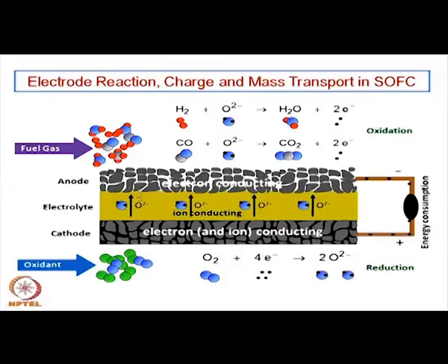Membrane, basically because it has a semi permeability only through oxygen, no hydrogen can go through, no other gas can pass through, only oxygen ion can pass through. So, it is basically acting as a membrane, although physically it is a very dense material. This oxygen permeability is because of the oxygen vacancy. So, it is the lattice oxygen that is going through, there is no physical pores in it. So, this electrolyte has to be completely dense, so that molecular oxygen diffusion is avoided.